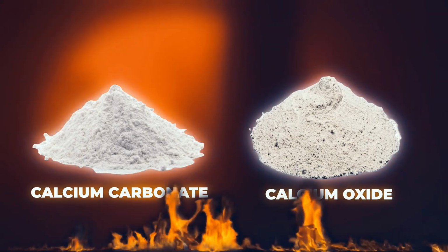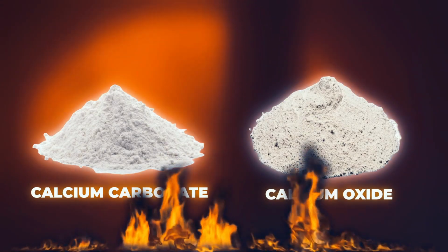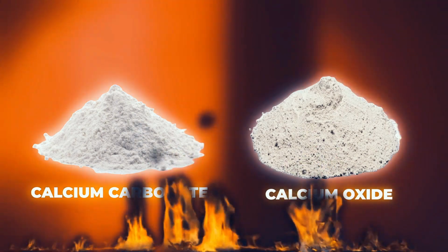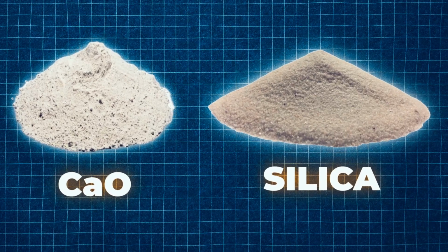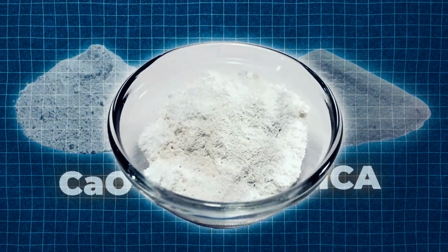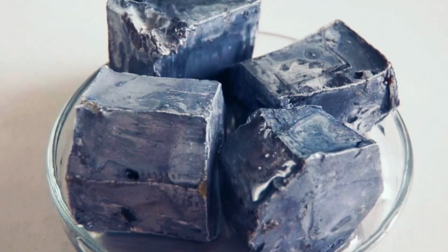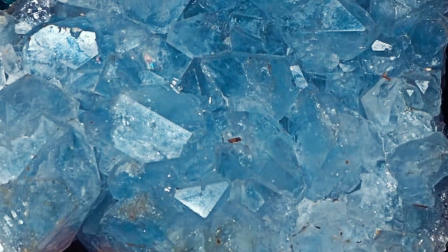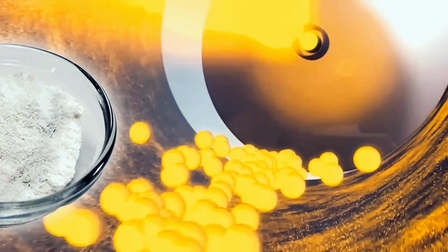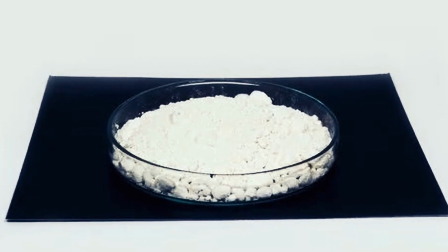Evaporation of free water. Evolution of combined water in the argillaceous components. The calcium carbonate, CaCO3, is heated up to make calcium oxide, CaO. When CaO mixes with silica, the calcium silicate is made. The liquid phase is formed when CaO reacts with the aluminium and iron-containing parts. Formation of the clinker nodules. Evaporation of volatile constituents, for example, sodium, potassium, chlorides, and sulfates. The reaction of excess CaO with the calcium silicate forms tricalcium silicate.